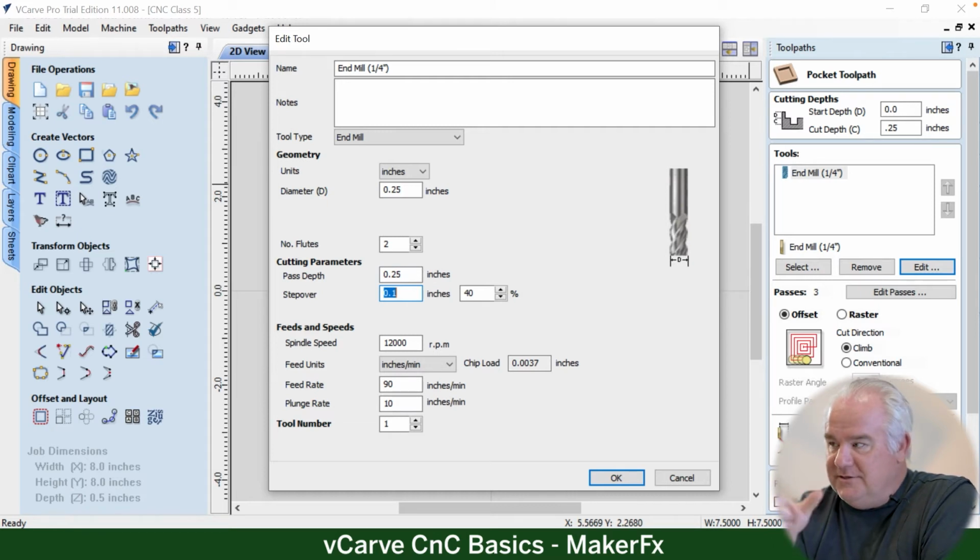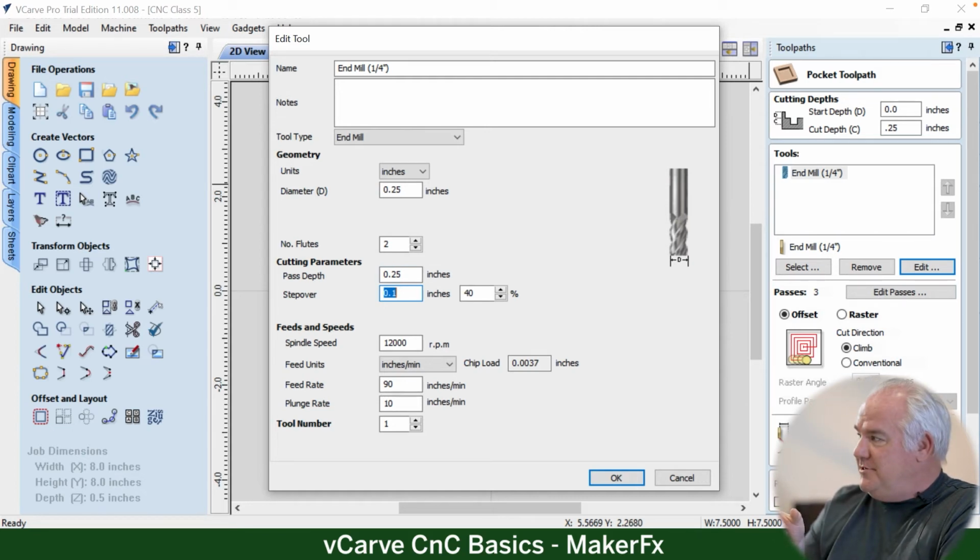When you're doing surfacing, it's really a pocketing toolpath. But if you think about that 1.5 inches, the first time it goes through a piece of material, it's probably taking 1.5 inches of material. So you go 1.5 inches one way. But we're surfacing, so now we need that tool to move over and come back, and do that consistently. When it gets to this side, it moves over and goes back, right? That jog to move over before it comes back is called step over. So how far do you want that tool to move over before you come back? That's going to influence how much material you're asking that tool to cut out of your material.